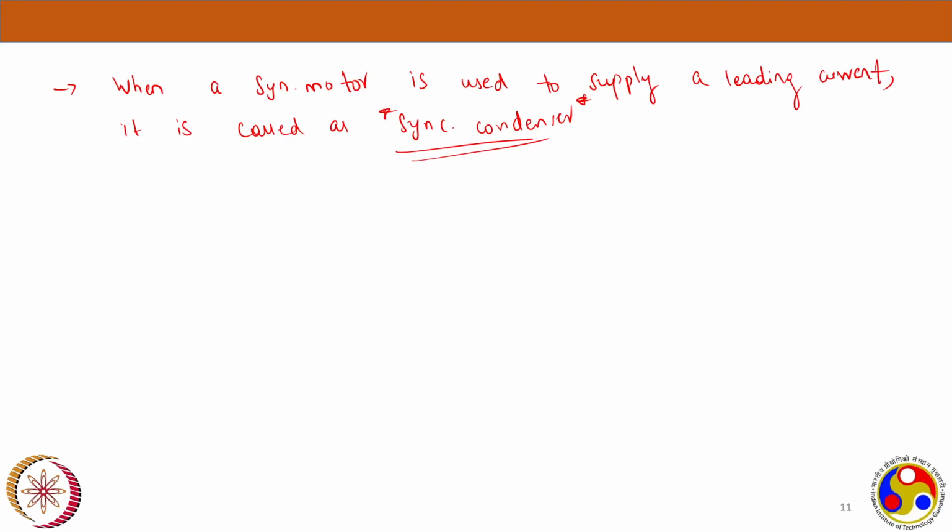Yeah, we generally use capacitors for the substation to improve the power factor, because the substation load is not known every minute. With a synchronous condenser in the overexcited case, it draws a leading power factor current. It will draw some current for the field too. So how is it beneficial in comparison to a capacitor?